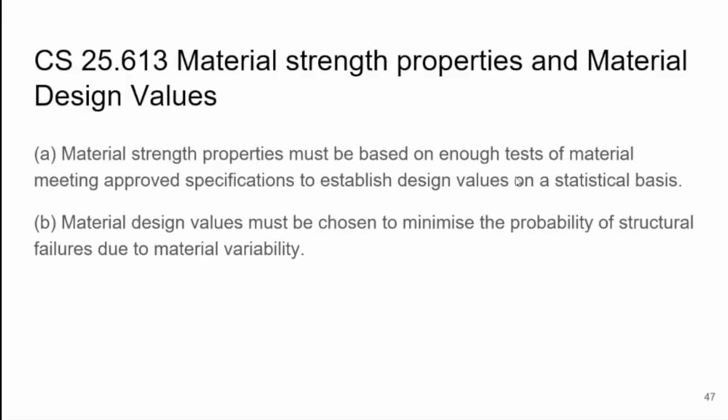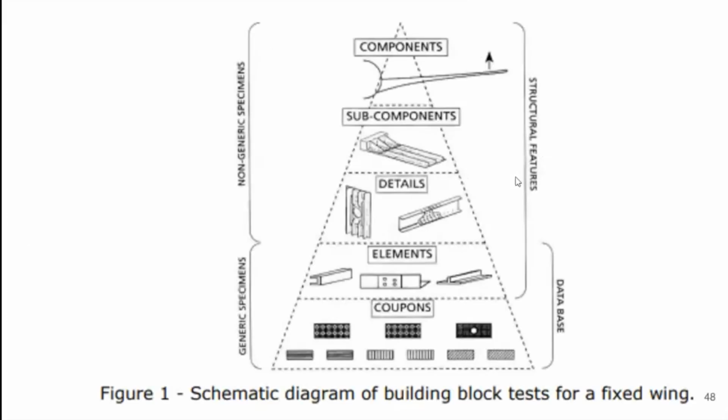And imagine this is not isotropic material. So this is anisotropic. So you have to have the value for the direction of the plies, and also you have to have the value for the laminate. So the structure is designed to a specific laminate, and then for each structure you have to develop, for example, the wing spar, the wing skin, they could have different values depending on the direction of the fibers being used in the laminate design. Again, famous pyramid, we have to do the test.